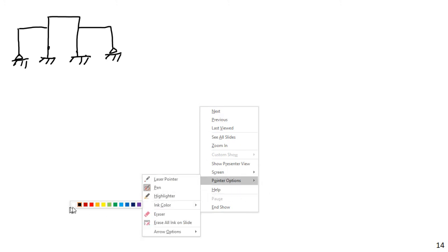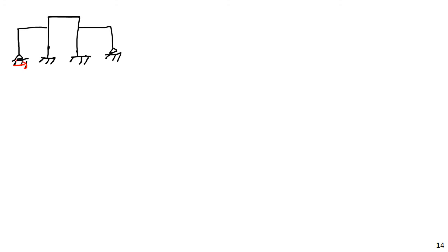And so then the support reactions: all three here for the fixed support, all three here for the fixed support, and just 2 on each pin. So in this case, n is equal to 1. I'm analyzing this entire frame as a single rigid body, so n will be equal to 1. R, however, if we count, is going to be equal to 10. So R is not equal to 3n, and R minus 3n, 10 minus 3 times 1, is 7. So this is indeterminate to the 7th degree.